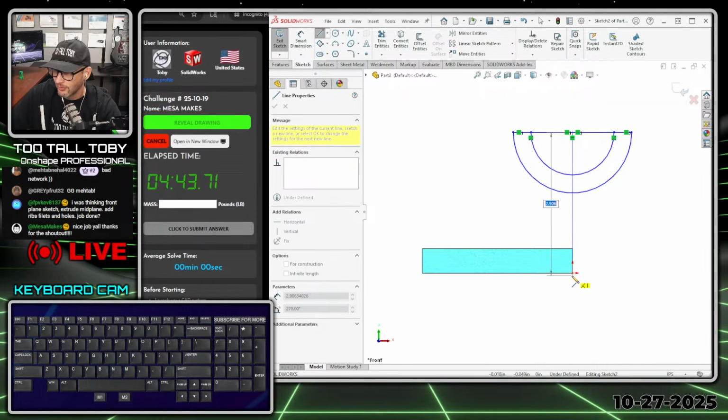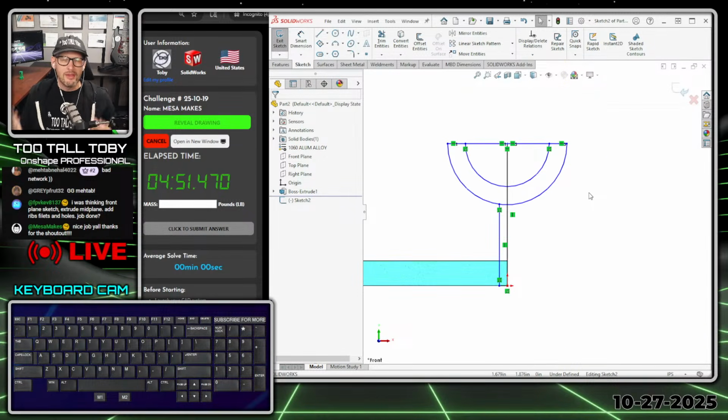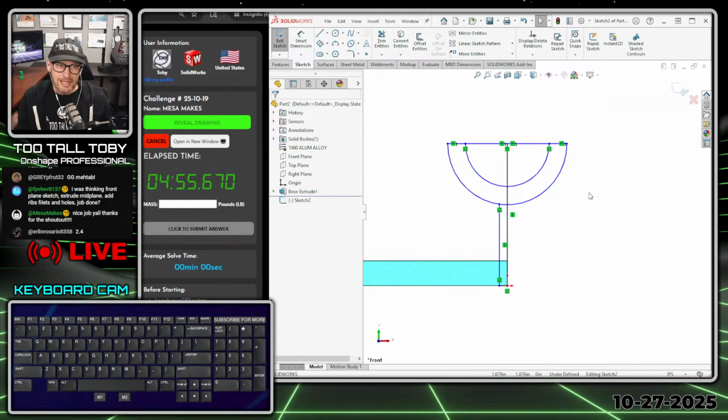and then select contours. The thing is, some CAD systems work better than others when it comes to working with contours. So if you were to create a sketch like this in SolidWorks, you just want to do a lot of practice so you understand what happens when you go to the extrude command. Does it default to take you into a thin feature? Do you have to remember to uncheck that option for thin feature? Maybe. We'll find out here in just a minute.